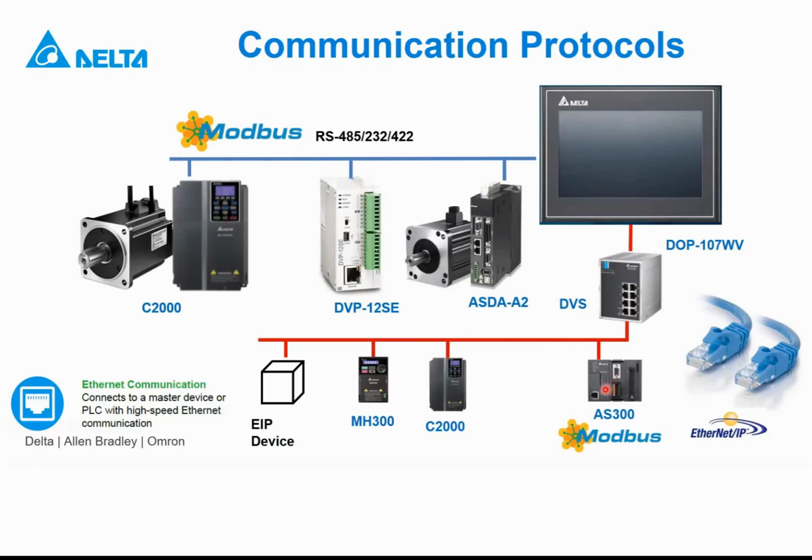Mostly the HMI can also read some sensors that give their signal over communication. If you have a sensor that transmits its output through communication, you can use it. But for a typical sensor that you need to connect to a measurement module, the HMI cannot handle that kind of sensor.